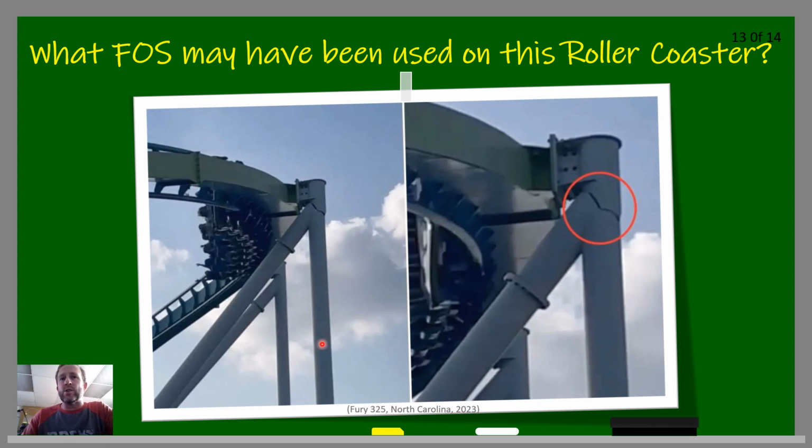And in this structure, when I look at it, I'm thinking they must have had a minimal floor print. Basically, why didn't they put some bracing coming out, for compression? This is in tension here. Maybe they had limited space and they couldn't, so they designed it this way. And remember how I talked about it looked like straws, like tubes, very sleek. So they were maybe looking for making a roller coaster that was minimalist. But now all that force is on these joints.